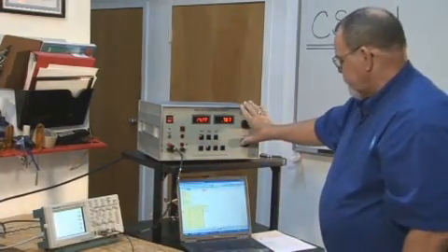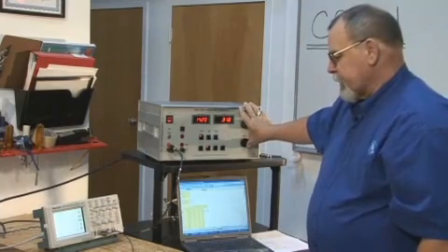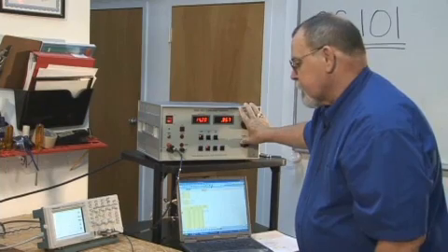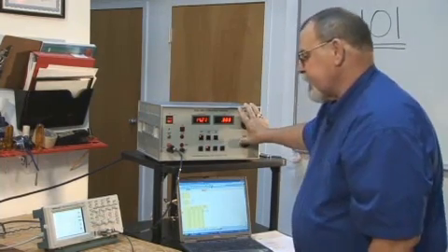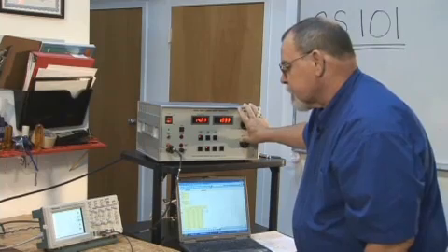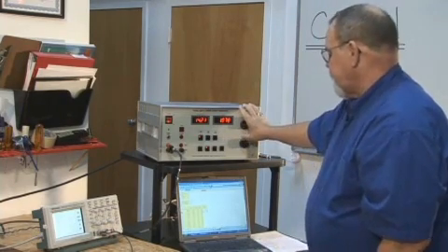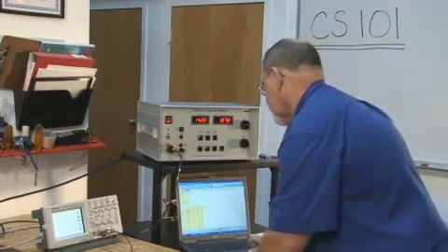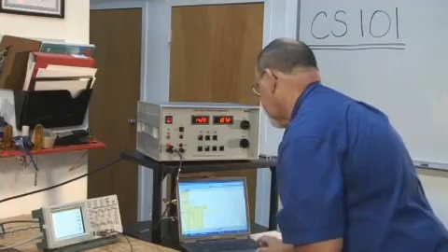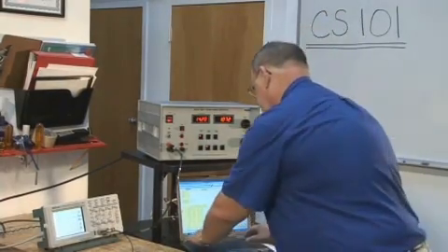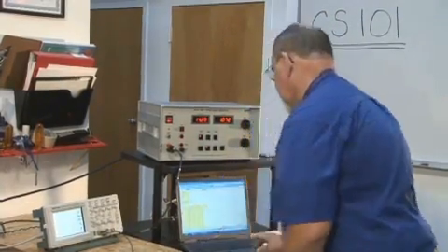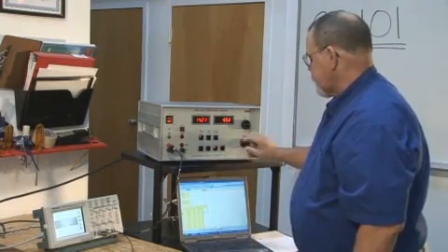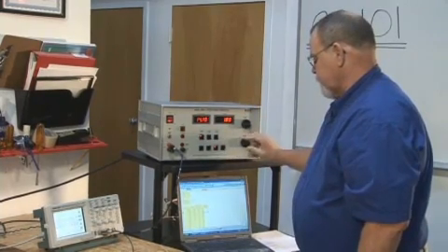We continue the frequency change, monitoring for a sinusoidal wave and above 6.32 volts. I'm maintaining this. 6.32 is still being maintained. I've got to 1 kilohertz. I will need to change ranges. Let me go ahead and record 1 kilohertz. 1 kilohertz, and I still have 14.2. And at this point, I'm going to change bands of my signal generator and adjust the frequency back to 1 kilohertz to resume at that point.